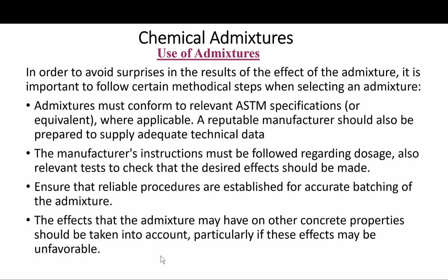So some commercial admixture formulations contain materials that belong to different categories, and their effects may change significantly at different temperatures. So again, knowing what the admixture is, what the side effects are, what the conditions are where it should be used, and how these side effects affect your concrete mix, all this should be known.